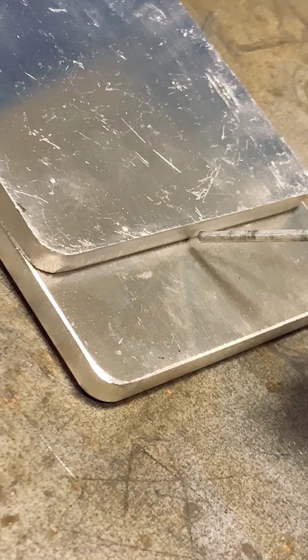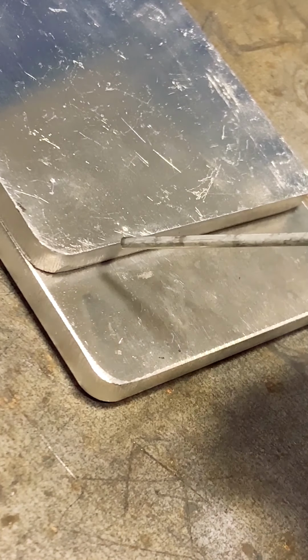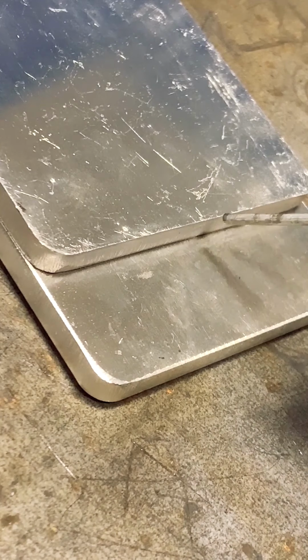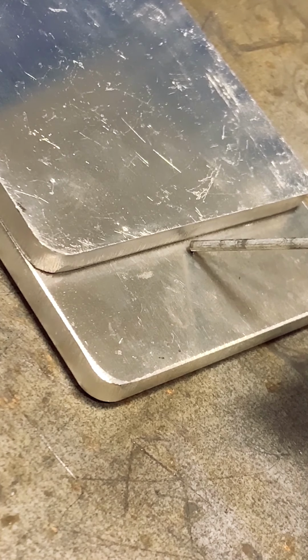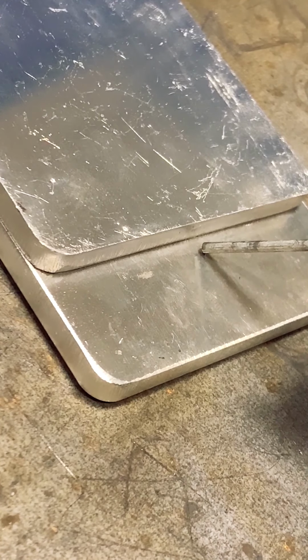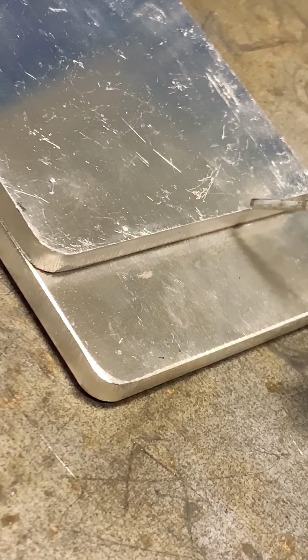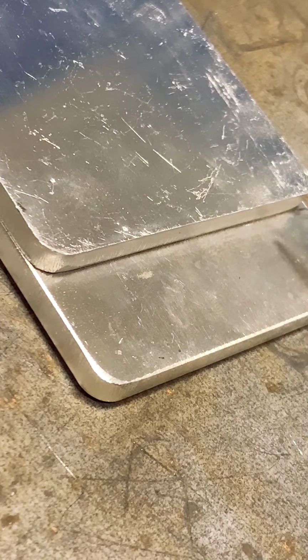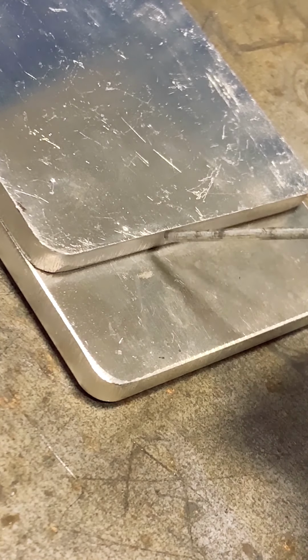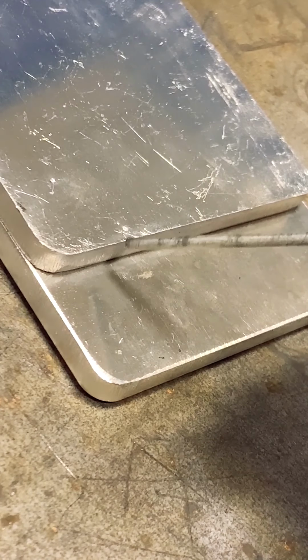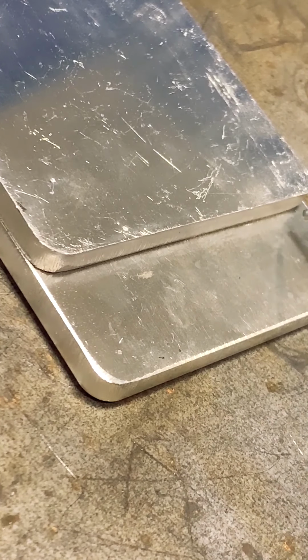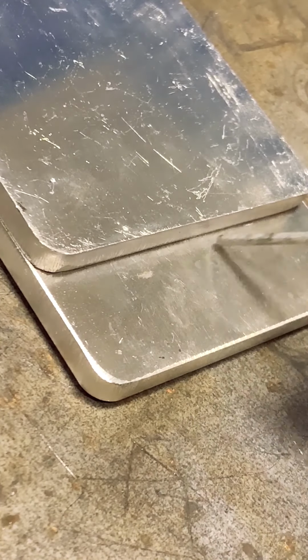Shooting straight in the middle in this case might end up eroding this shoreline, as I like to call it, even more. I may want to do probably either the diameter of an electrode, if not half the diameter of an electrode, away from the wall for my placement on joint, so that I can successfully burn in some of this edge a little bit, but also add some filler material to backfill this space as I erode away a little bit of that shoreline right there. And then I won't get such a raggedy profile there.